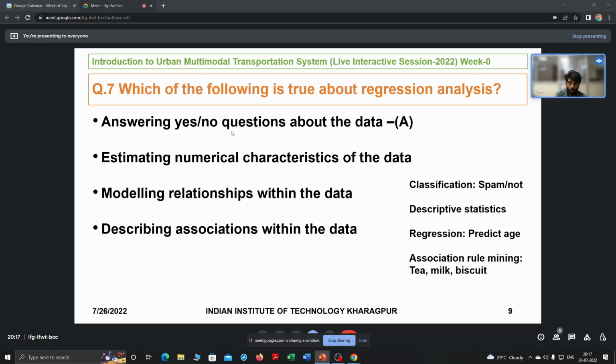In transportation, for example, speed along a horizontal curve may depend on geometric characteristics like the width, the acceleration of the vehicle, and the sight distance. Those are x1, x2, x3 and so on. So what is the relationship between y and x? If you have one variable, it can be a linear regression, y equals mx plus c. If not, it may be m1x1 plus m2x2 plus c and so on, right? This is called regression analysis.